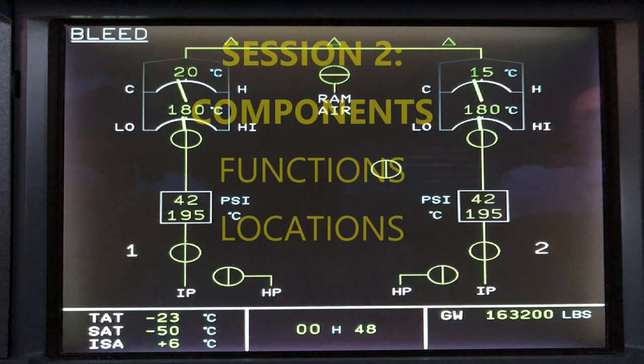Okay, let's start with describing one of them. This is the bleed transfer pressure transducer. It's important I started with this besides the cooler, because the transducers are the ones sending those signals to the BMCs, right? So where's the input coming from? It's coming from the transducers as far as pressure. Those are sent to the BMC, then to the SDAC, and it goes to the ECAM bleed page. That's the chain of events, input to output, going straight to where the pilot can know what's going on.